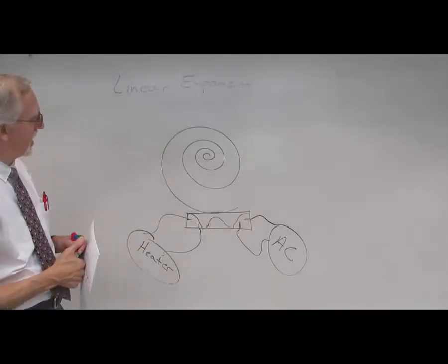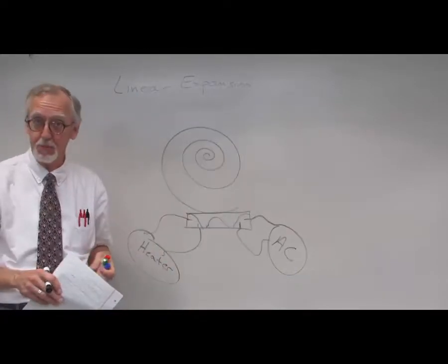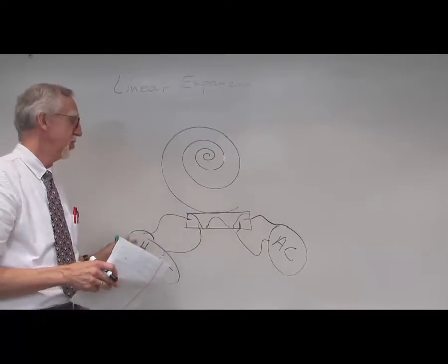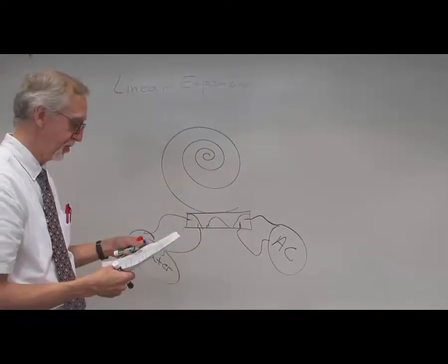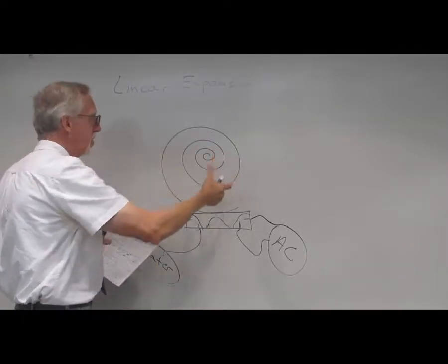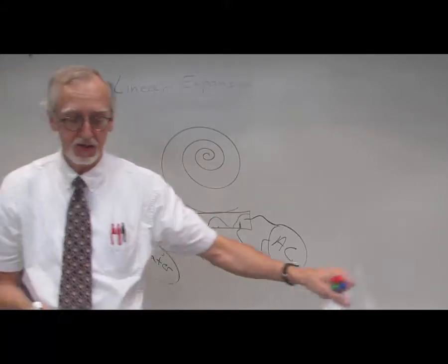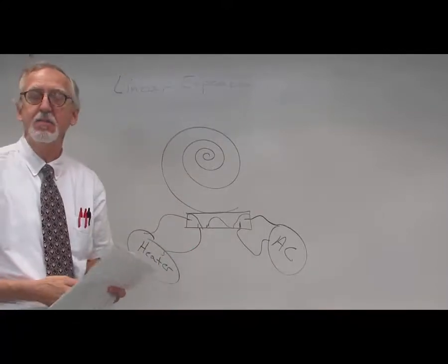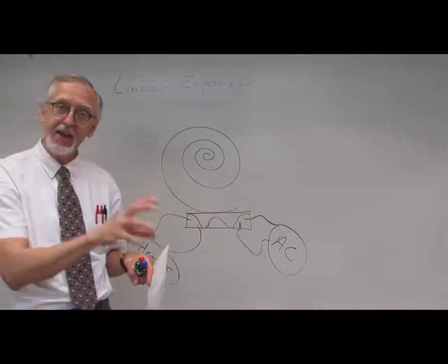And so the thermostat was designed to maintain a somewhat regular temperature for the house, either turning on the air conditioner or turning it off, turning on the heater, turning it off, to try and maintain a regular temperature. And you could adjust that by rotating this coil one way or another to determine what temperature you wanted your house set.